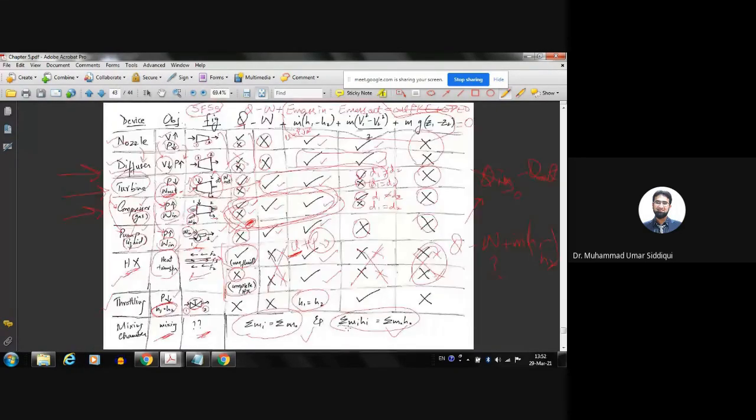Anyways, if we look at the summary here, we discussed the application of first law of thermodynamics to open systems under steady state conditions. It's normally said SFSS, which is basically steady flow, steady state systems. Since these are steady state systems, the change in internal energy, kinetic energy and potential energy terms with respect to time will be zero. The only terms we consider are the ones occurring across the boundary. So you'll have Q minus W plus E mass in minus E mass out equals 0.